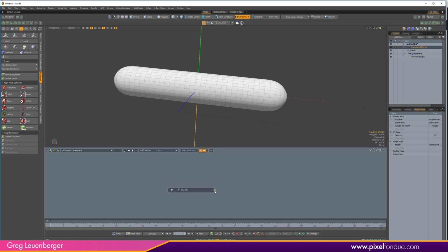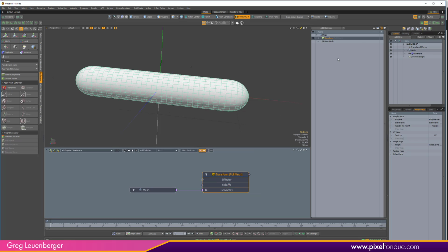And when I clicked that button, it did two things. And this is how deformations work in MODO. First of all, it added an influence, and this also appears in the deformation stack here. Or actually, it used to be called the deformation stack. Now it's the mesh operations stack, right? Because now you can mix mesh operations, which create or destroy geometry, with deformers, which just manipulate existing points. And you can move those up and down and do all kinds of cool stuff with them in the stack. And there it is in the stack.